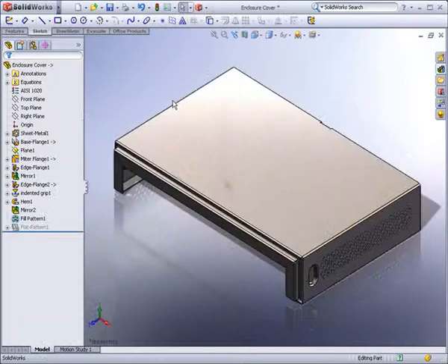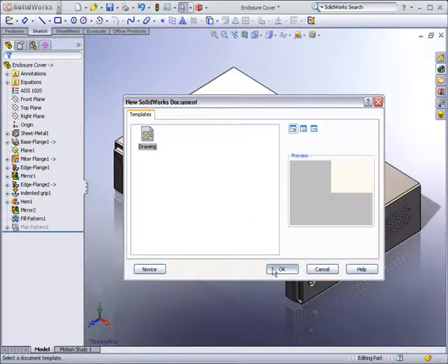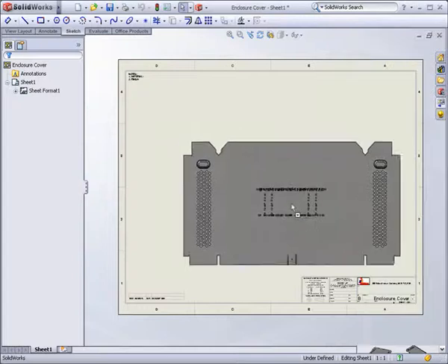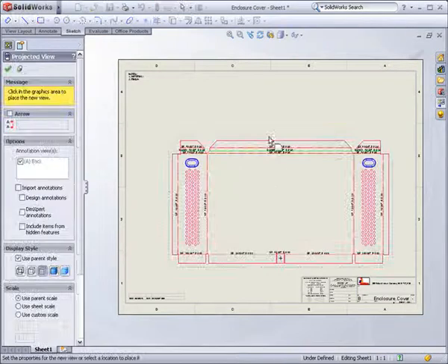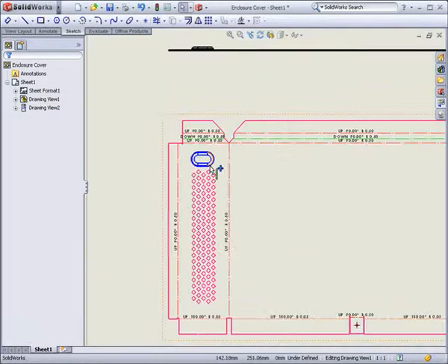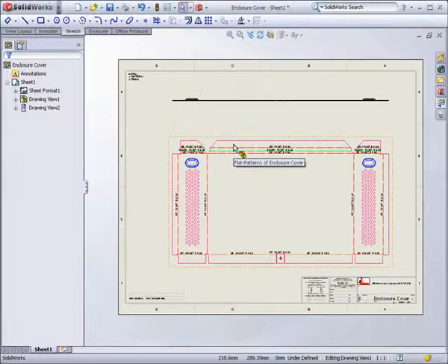With SolidWorks, you can create 2D drawings at any point in the design process. Here, we open the part and create a drawing from the part, automatically adding the flat pattern view and the edge view. SolidWorks automatically adds all the required sheet metal bend lines. You can set up SolidWorks to color code all the sheet metal elements required, thereby enabling seamless transfer to CNC machines via DXF.